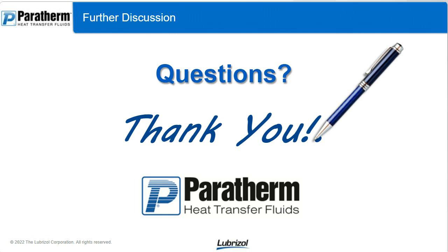The only time flash point really comes into consideration is if you have a catastrophic failure of the fluid where you have a leak into the heater box, and then you have an enclosed space with no ventilation and obviously extremely high temperature. Under that circumstance, the flash point of the fluid no longer matters. The conditions inside that heater box are going to be well above whatever any flash point of any fluid is. So under normal operating conditions in a well-designed system, your flash point never comes into consideration because you don't have that combination. There's three necessary items: ignition source, oxygen, concentrated vapors of a heated fluid.